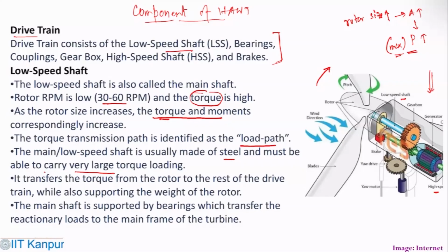We will consider these things when we look at the dynamics aspect of the turbine. This shaft transfers torque from the rotor to the rest of the drive, while also supporting the weight of the rotor. Obviously, this shaft is supported by bearings, which transfer the reactionary loads to the main frame of the turbine.